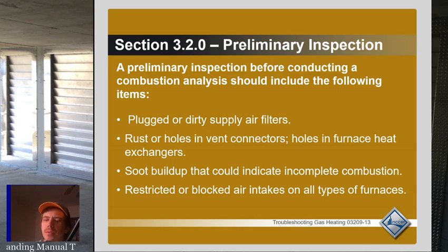Soot buildup. If you see soot in equipment, pay very close attention to what's going on, because a lot of soot buildup is bad, and a lot of times it goes unnoticed for a long amount of time. But that is an indication that you have incomplete combustion, that you don't have enough air getting to the equipment, or something's burning improperly. It could be low gas pressure. Things like that can cause soot buildup as well. So you want to look for any of that.